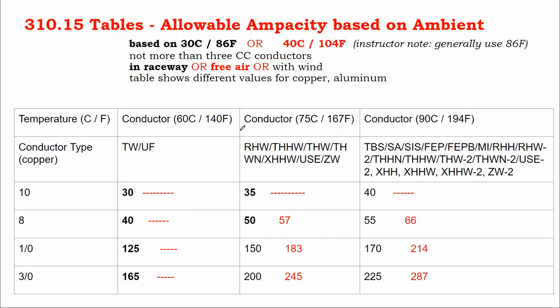And then different cable jackets, we've already pointed out they have different temperature ratings, and so a cable jacket with a higher temperature rating can hold more amperage and have less temperature derating due to heat than a cable that's not designed for a harsh environment. And that really comes into play when you start using indoor cable versus outdoor cable. They can make indoor cable a little bit cheaper, and that cheapness means you can't do as much with it.